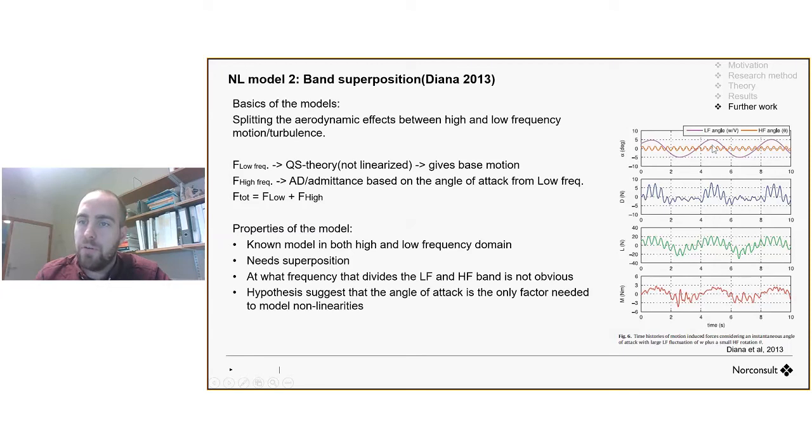They took a slow harmonic first, and then they have a fast harmonic also. If I see the forces, they are really varying depending on the slow harmonics and what angle of attack the small harmonics give. So this is a linearized version, it has some time linearization compared to the angle of attack.